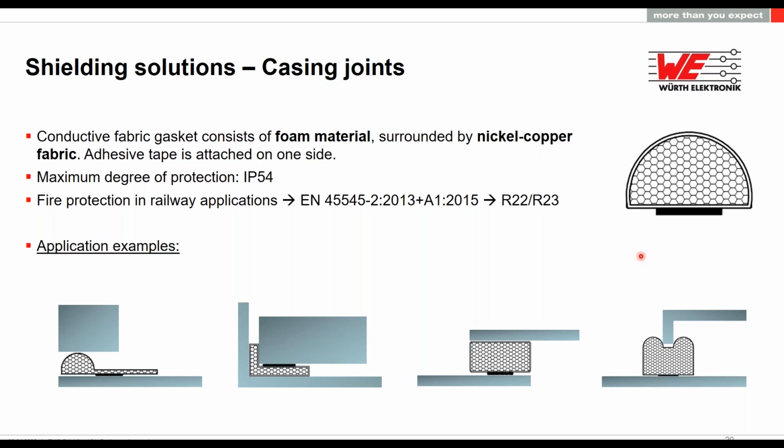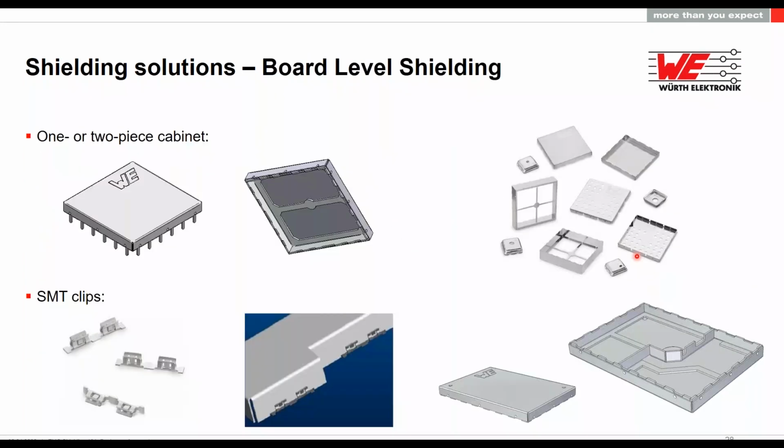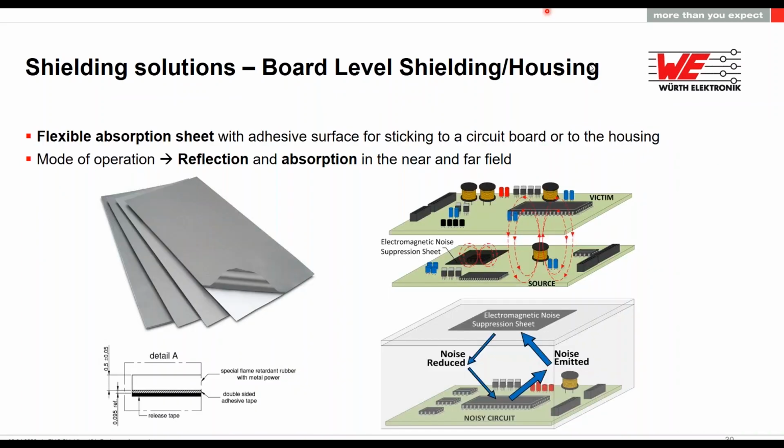Yes, of course, it's possible, and it's quite common, I would say. We have requests like this from our field application engineers and sales engineers about these designs many times. So when we have inductors that are problematic, that are radiating too much noise, then we can seal them in this way we showed before. You can just stick some ferrite sheet or absorber sheet on top of it, and then we are preventing this noise from coming out of the inductor.